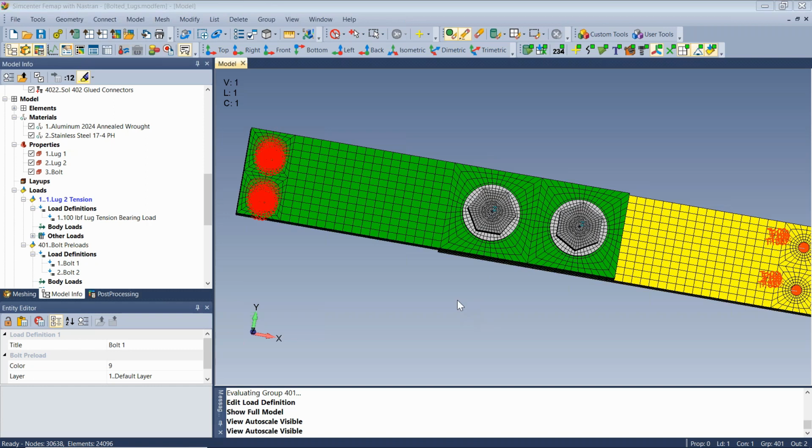Are there any questions to explain the contact settings? For the documentation on the contact settings, you should refer to the Nastran multi-set nonlinear users guide. There's a difference between no separation and sliding contact. No separation means that once the two surfaces come into contact, they can't split apart.